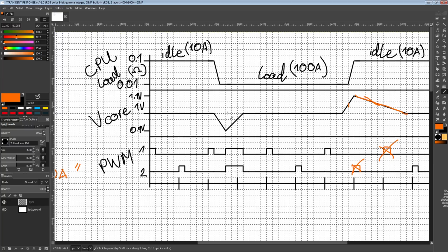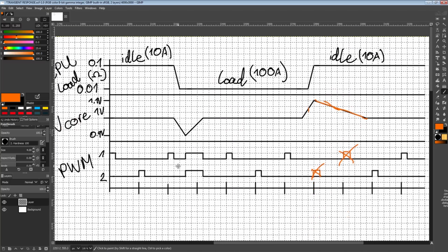But there are some motherboards which are exceptionally bad, and on those you need like 100 millivolts or 150 millivolts more voltage to hit the same clock speed as on a better motherboard, because your undershoot on that motherboard is down here somewhere, right? And it's just like, well, that's bad, right? Your voltage regulation is completely out of whack, and therefore your overclock is horribly unstable.